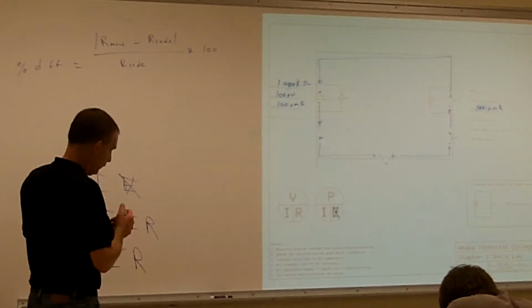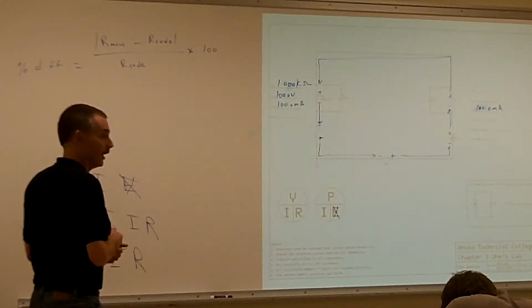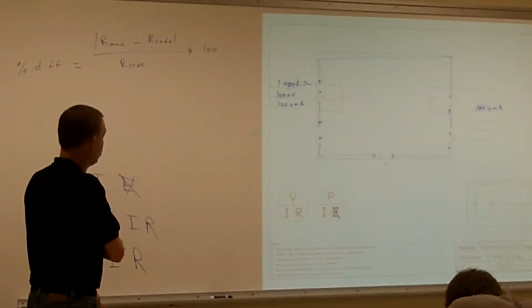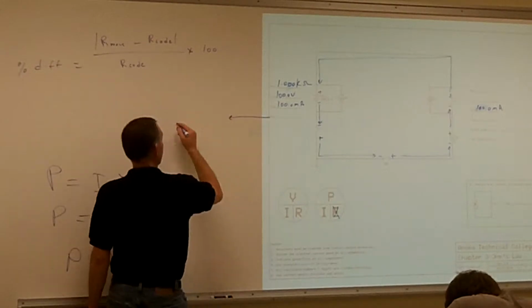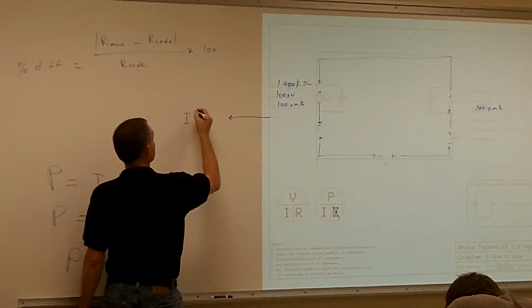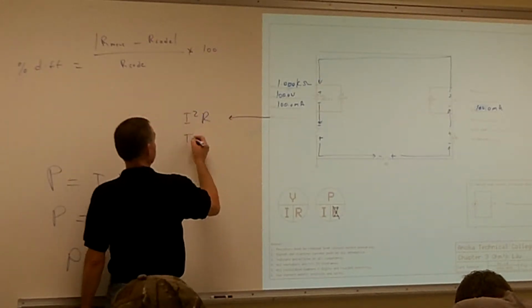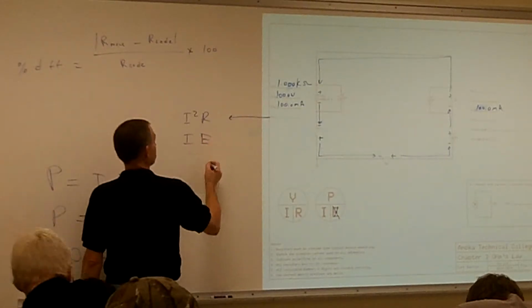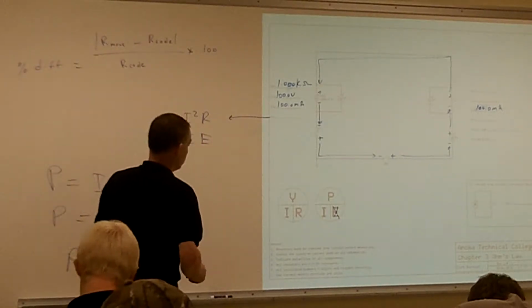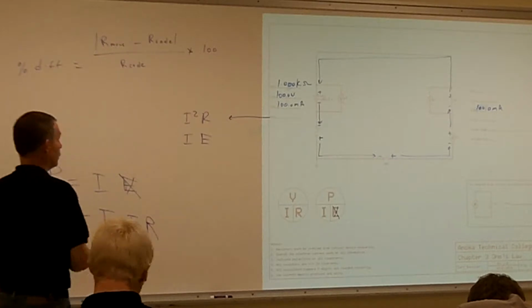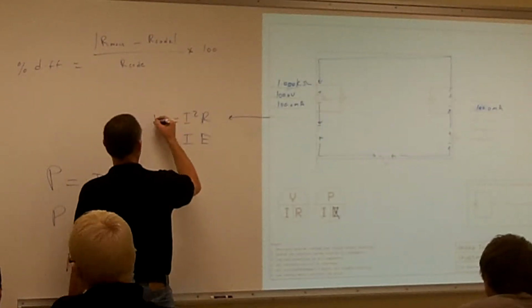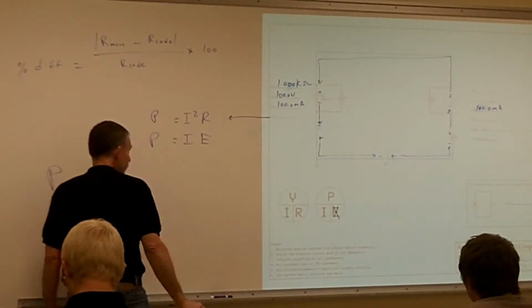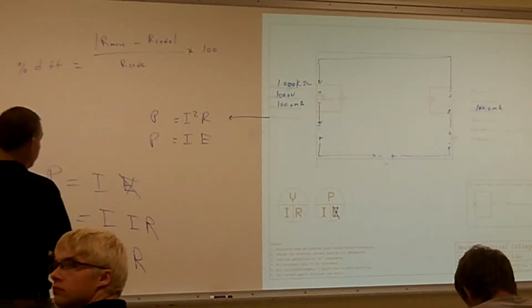It's also good to figure out your power. We might as well figure out our power. What would I use to calculate my power? I squared R would work, or I times E would work. Either one of those equals power. It all depends on what information you have.